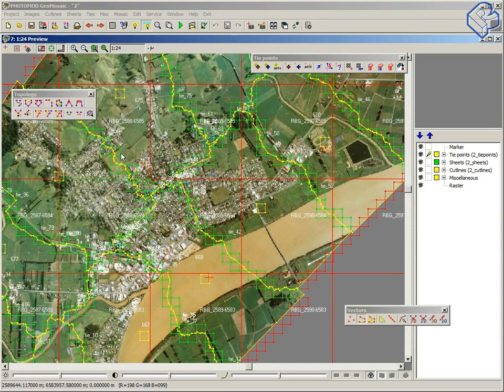For example, if we have some hole between images, in this case we have to change cut lines to make these fragments green, to give enough information in this part for local adjustment. In this case they are red because it is a border.